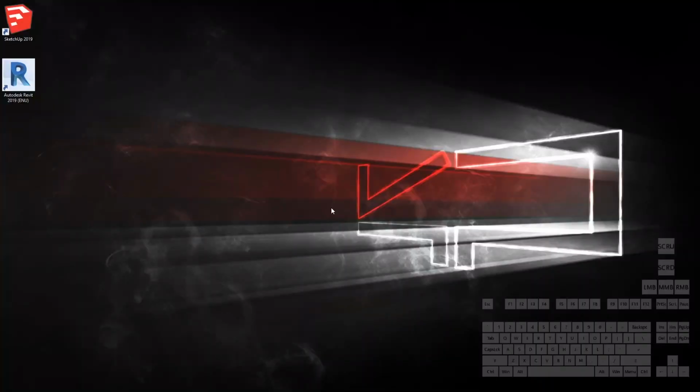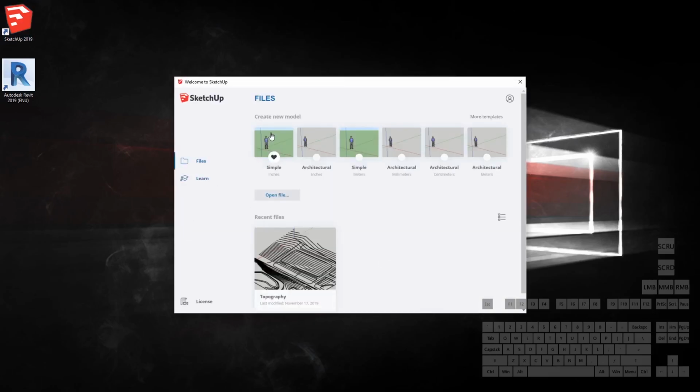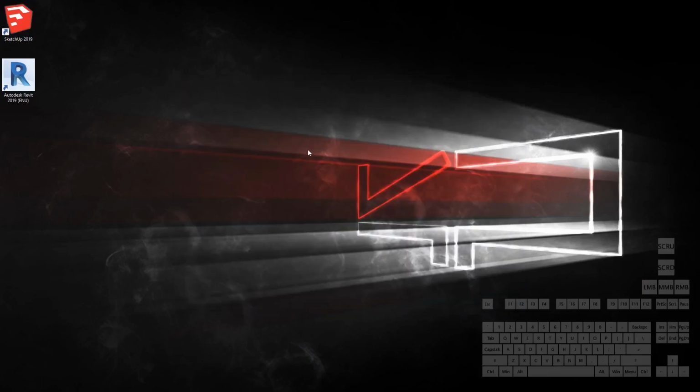I'm going to demonstrate how you use SketchUp to generate topographical data, and then we're going to use that topographical data and insert it into the Revit environment to generate a topographical surface. So we're going to open SketchUp and we're going to select an architectural template.